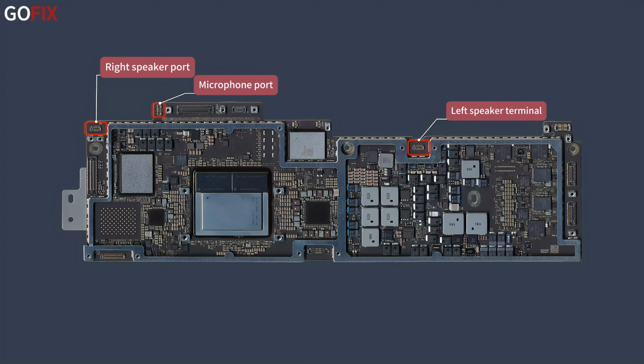Next is the encryption chip, U1950. It's encrypted and bound to the SoC and the computer's main hardware. If the data inside is lost or the chip is damaged, this computer will lose its repair value. Therefore, you need to be extra careful during repairs.